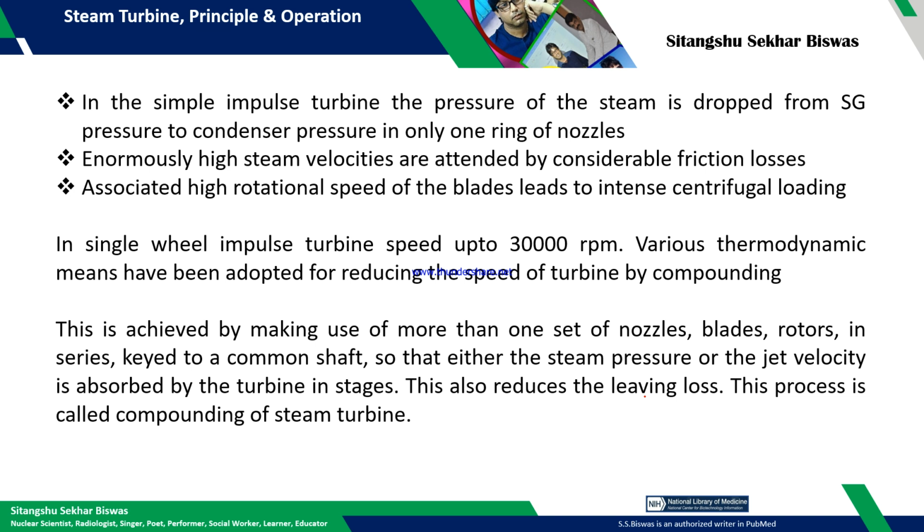Okay, and once there is a high rotational speed or angular speed, this will cause centrifugal loading. Small residual unbalance can cause huge vibration, so to handle that situation will be very difficult.